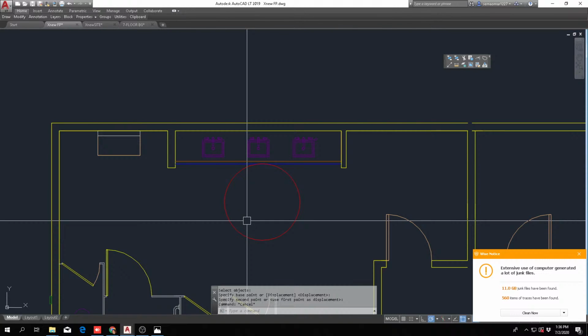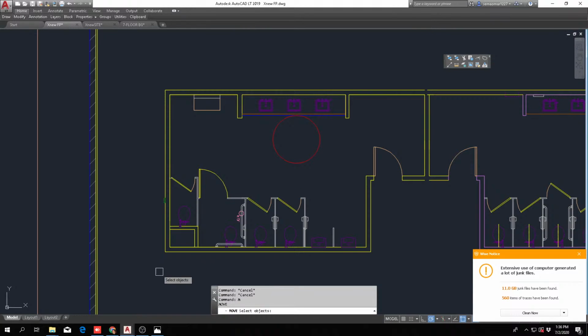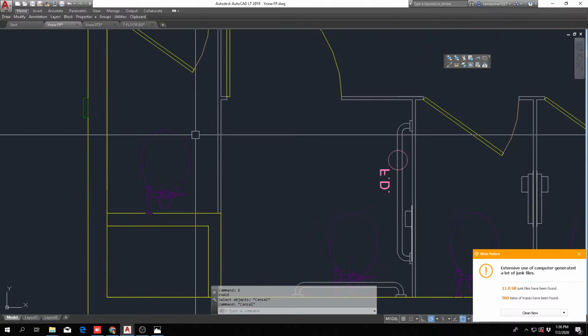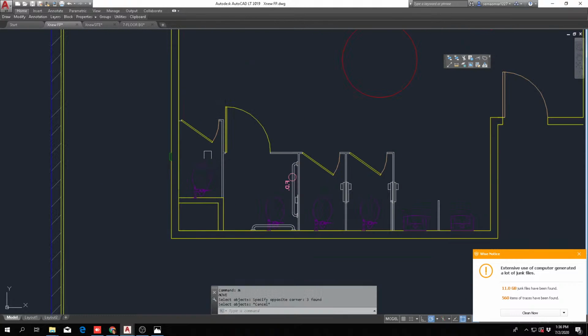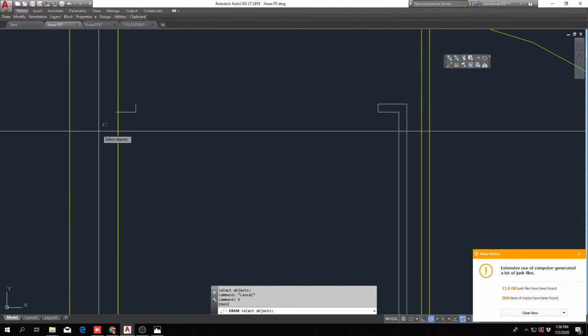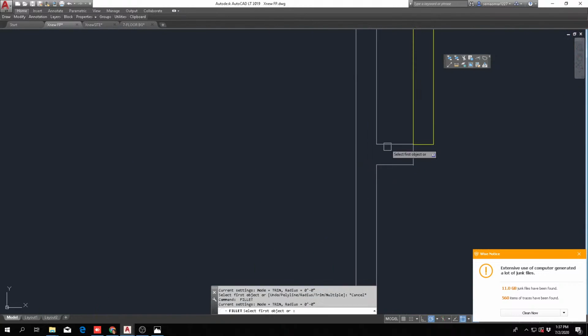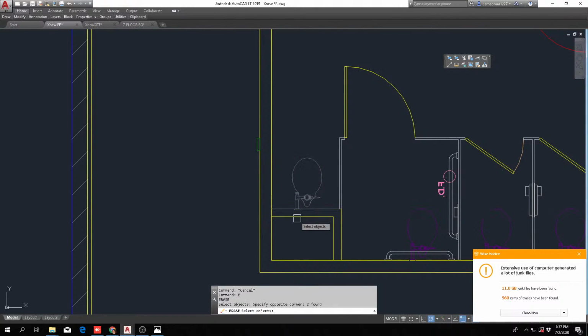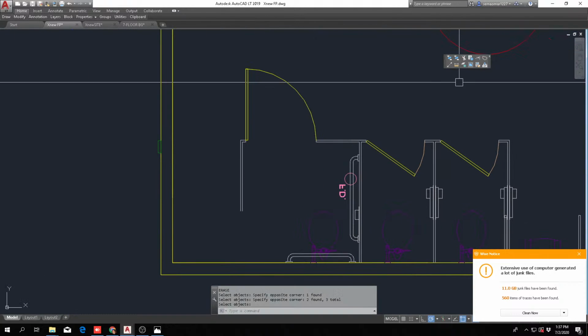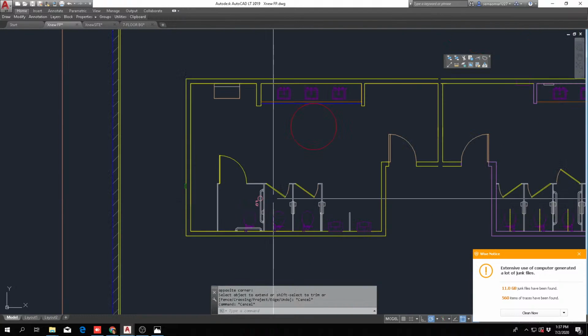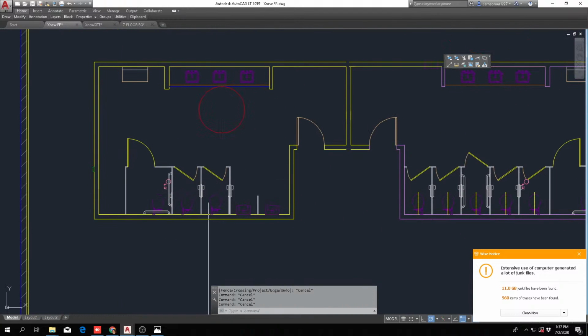You can bring in all those spaces for the handicap when you pull the door, when you push the door and stuff like that, and that's gonna work perfectly. But when you're in a rush and you just want to start drawing something and present it to your client really fast, then just draw a circle of a 5 foot diameter, and that is going to guide you where not to put a wall.